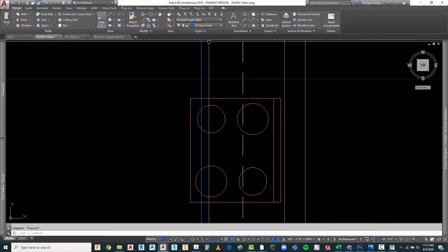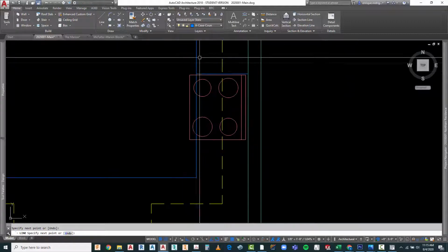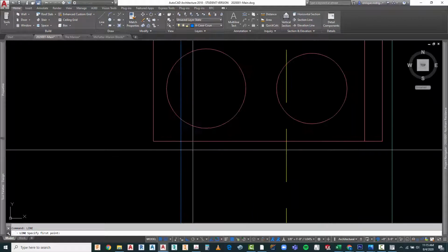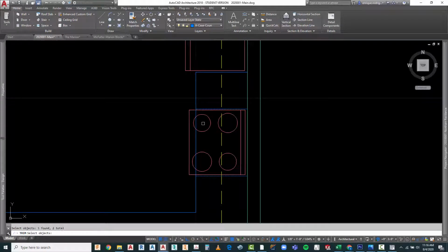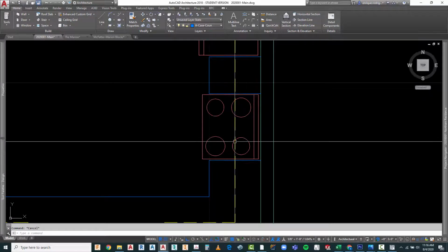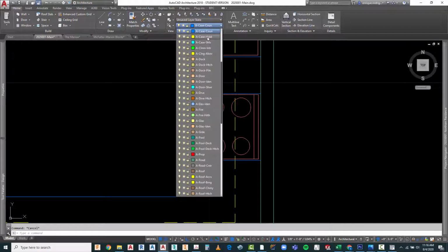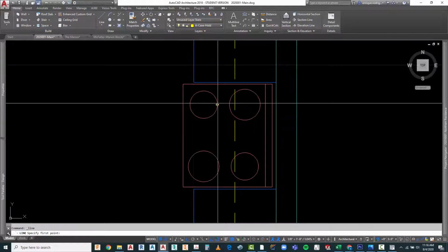And with my A case counter layer, I'm going to leave a space where that countertop can go. So I'm going to trim, and trim that out of there. Now, in some cases, we would actually bring this further out to make sure that the hood covers that. We can use actually the same layer that we had, A case hidden, and we could probably just bring it about to here.